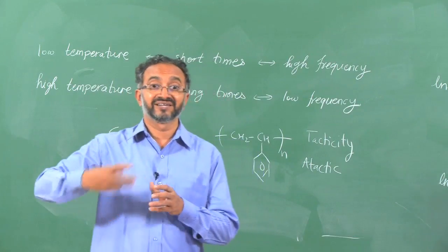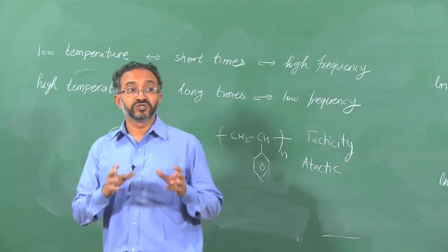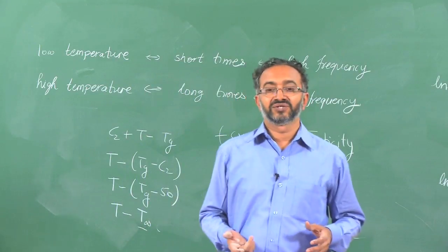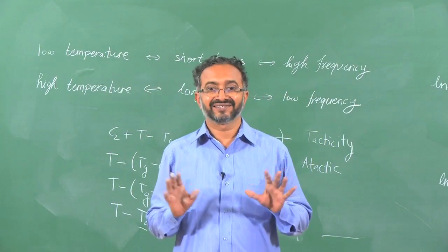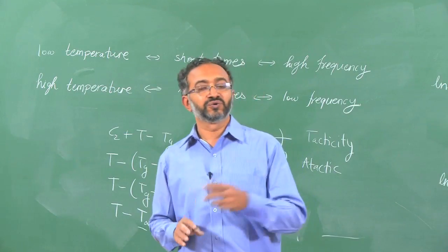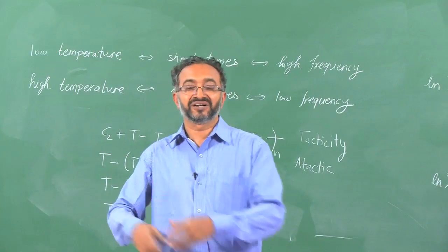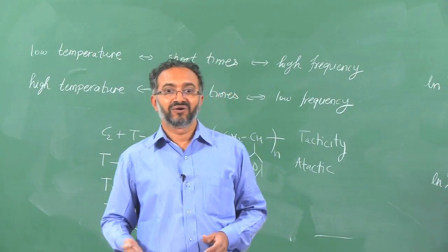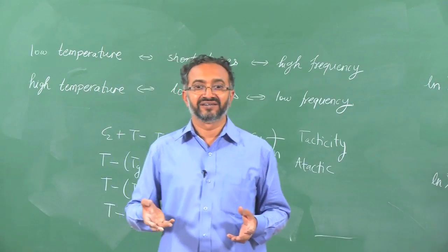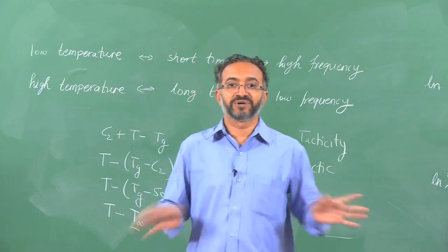So, fundamentally there is a structural change in the material. That is a good indication, and of course, you will need to have a hypothesis on the other side as to what might be happening. So, at 300 for PET you will say that yes, some chain scission, some oxidation reactions are happening. Then you can do a spectroscopic analysis to see if a material which was subjected to 300 is showing any other bonds, or you can do a calorimetric measurement to see if there was any heat of reaction, because melting and all is finished by 250.